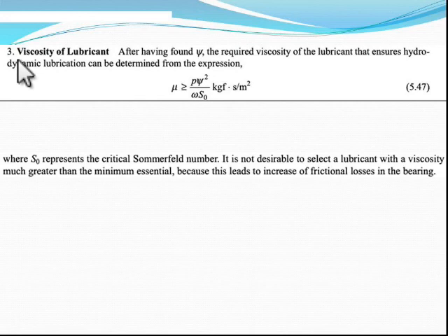Another very important property which affects bearing performance is the viscosity of the lubricant. In general, one can very easily understand that if one uses a very highly viscous lubricant, the load carrying capacity will be high. That is simply because of the density of the oil that is being used, and it is very difficult to displace that oil. So generally the load carrying capacity of higher viscosity lubricants is higher. On the other hand, if you have a very thin and less viscous lubricant, the load carrying capacity will be very low. So based on this, one can choose the lubricant.